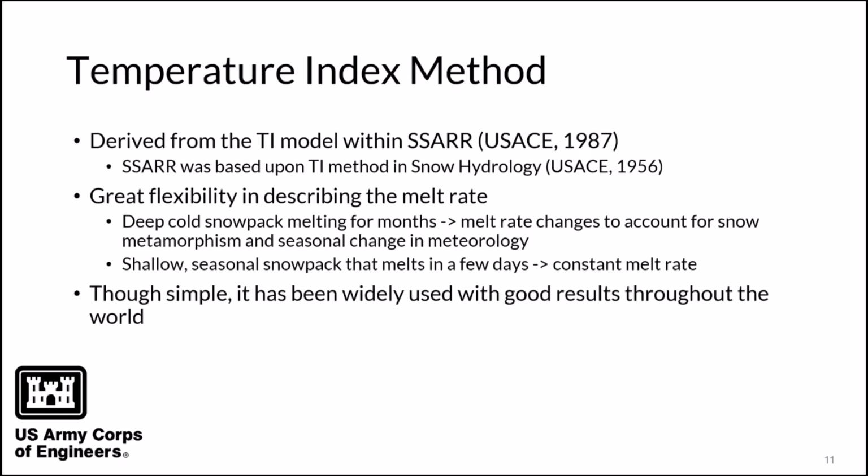As Natasha mentioned earlier, you get to choose, right? In the past, you got to choose one snowmelt method for the entire modeling domain, which was within the meteorologic model. But now that we've moved that to the basin model, you can choose which snowmelt method you would like to use for each individual subbasin. So keep that in mind as I describe some of these methods. Some of them are more complicated than others. Just because they're in there doesn't mean that you have to use them. You get to choose within HMS, which is a really powerful thing.